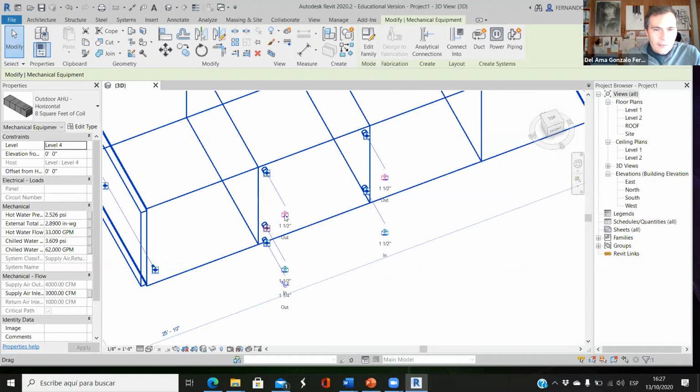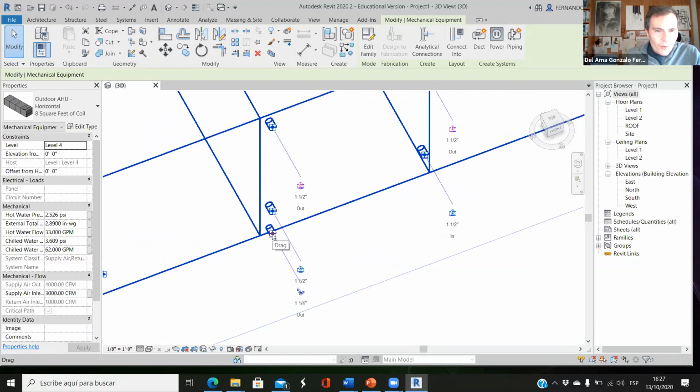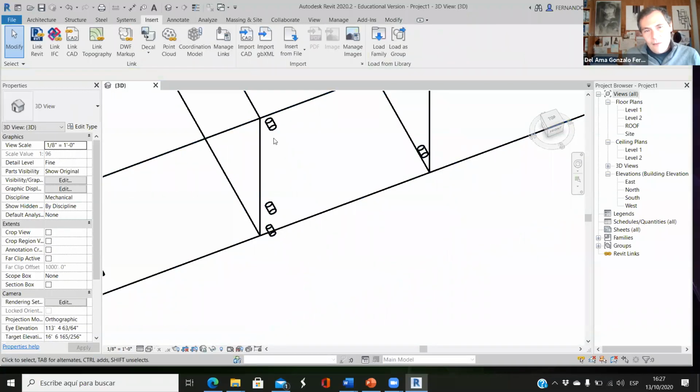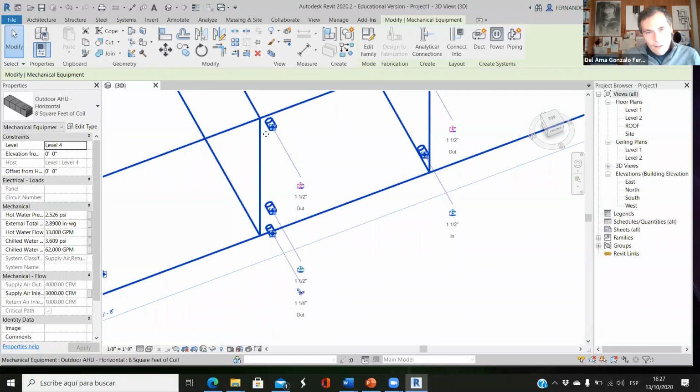How do I know that this is the cooling and this is the heating coil? When we have this to get rid of water, this is the cooling one, because the water cools down in the cooling coil, and the water condensates in the cooling coil. Okay, so when we have this coil with three inlets or outlets, 1, 2, 3, this is the cooling coil.